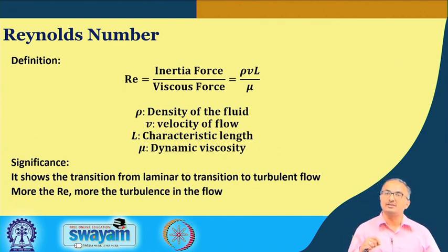The flow rate also dictates the pressure drop. Because as we increase the flow rate, we find that the pressure drop through any particular element will also keep increasing. And many times in fluid mechanics you have found that the pressure drop is given as a function of the Reynolds number. Okay. So, we sometimes call all these things thermohydraulic characteristics. Thermo means the thermal characteristics, that is, the heat transfer rates, and hydraulic means how the pressure drop is affected by the flow of the particular fluid.